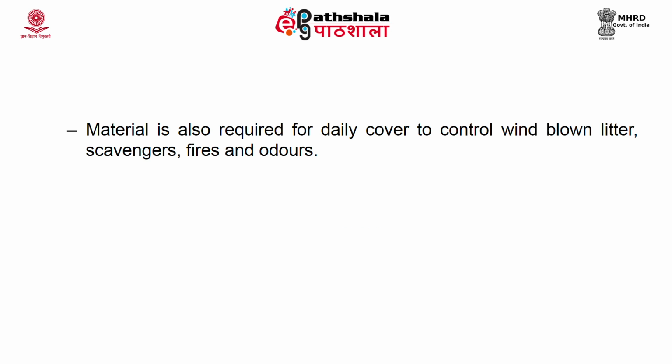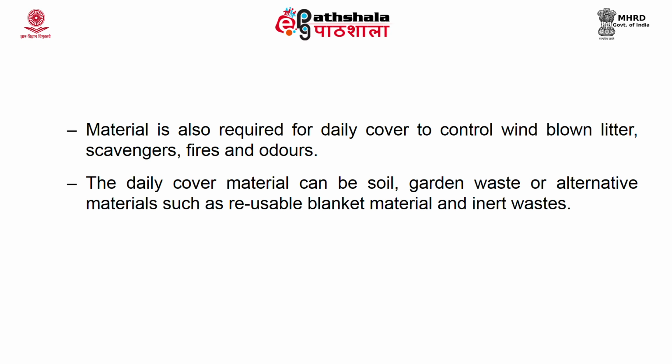The material is also required for daily cover. Apart from the liner system, these materials are also required for your daily cover. I told you daily cover will protect from wind blown litter, it will keep out insects and rodents from burrowing into it, and it will also avoid scavengers, fires and odor. Not only soil material can be used as daily cover, even garden waste or alternative materials like reusable blanket material and other inert waste can also be used as a daily cover.